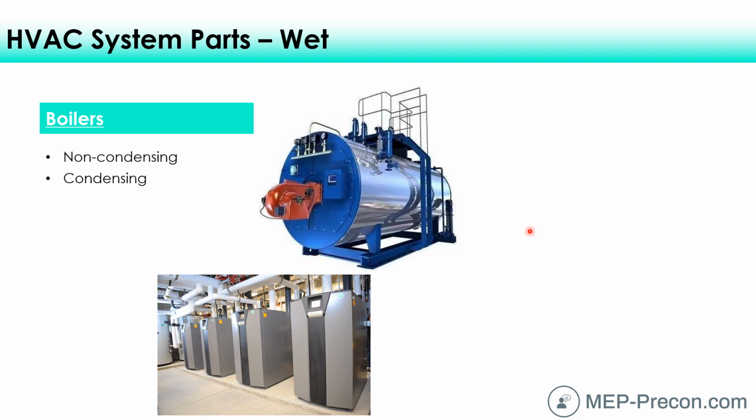what you pay in energy that you burn, the fuel that you burn, if it's either propane or natural gas, goes out the flue out of the roof. Well, why don't we take more advantage of that? Why can't we get these things to be 95, 96% efficient? Well, we can, and that's what a condensing boiler is for.